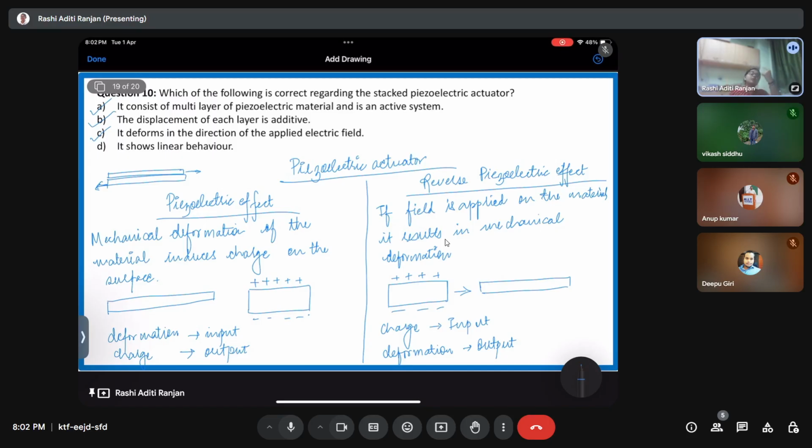So if I talk about that, the elastomer possesses viscoelasticity. Okay, so because of the viscoelasticity, there is dissipation of the energy. So if I talk about that kind of a piezoelectric elastomer, definitely the change of deformation is going to affect the damping property as well. Okay, I hope this is clear.